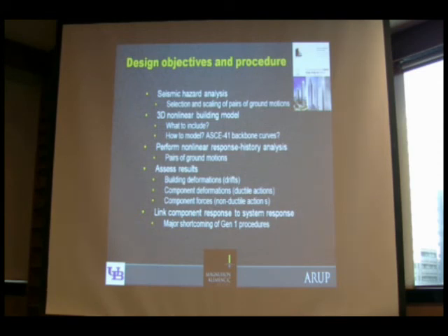So if you're looking at rotations in a beam, for argument's sake, then we have acceptance criteria for those deformations for the performance objectives of immediate occupancy, life safety and collapse prevention. Increasing levels of damage, increasing values of that plastic hinge rotation. But one goes through this performance check component by component, so quite similar to traditional practice. But at the end of the day, we link system response to component response.